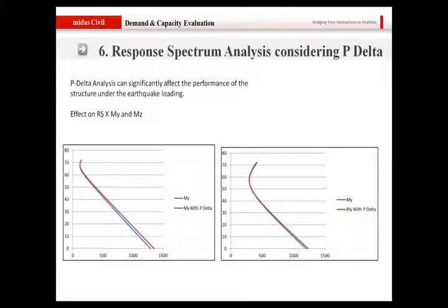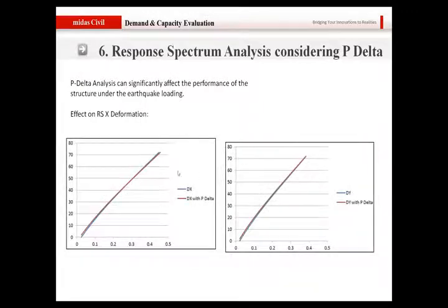So sometimes you have to take into account the P delta analysis, and Midas Civil does provide you with this feature. You can perform a P delta analysis while considering the response spectrum analysis. And again, I checked the deformation, and you can see that the deformation with the P delta analysis is a little on the higher side. So basically, when you are taking into account the P delta effect, the demand will be on a higher side.